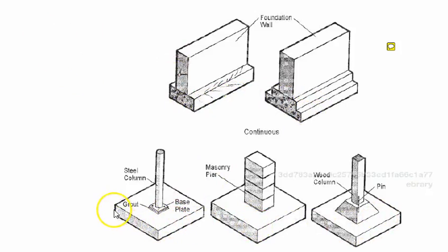Again, you just don't want to throw down a blob of concrete in the ground. It's a waste of material. It doesn't transfer the loads, and that's what these devices are for, to transfer the loads that they're carrying efficiently to the soil beneath them so that you have a stable, strong structure. So you need the forms to make an accurate, neat form or shape so that you can accurately transfer loads.